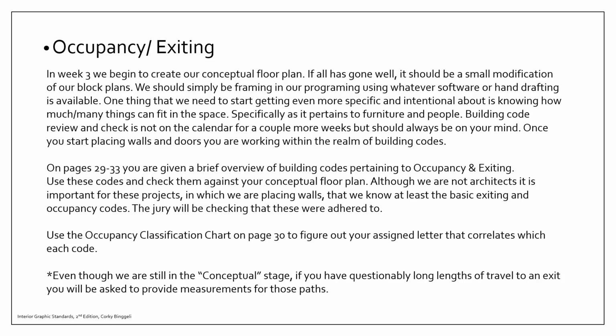Travel distance is measured in a straight line from the most remote point through doorways, unless furniture or equipment requires measurement along the actual path of travel. When the path of travel includes an unenclosed stairway, the distance is measured along a plane parallel and tangent to the stair tread nosings in the center of the stairway. So that's just a lot of information which doesn't necessarily apply.